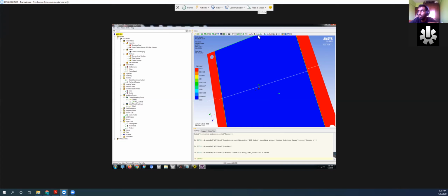Now, another thing that you want to check is fiber direction. So when you go up here, you want to click on the neon green, and when you hover over it, it should show fiber direction. So if you click on it, it will. Okay. So what will happen is you can see that there's little lines that appear.